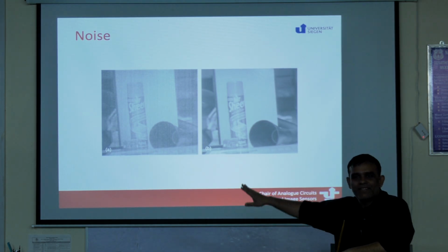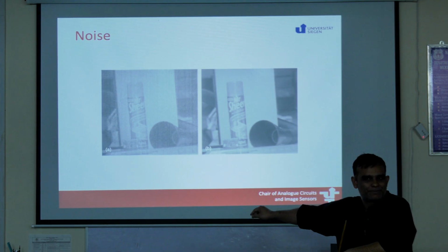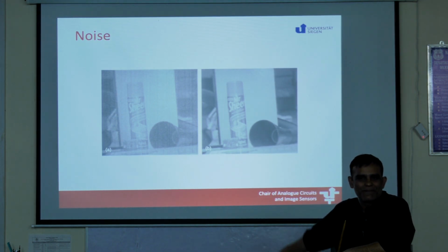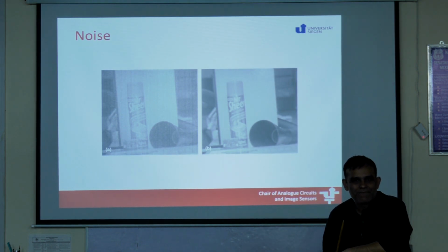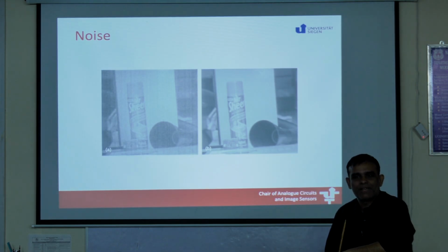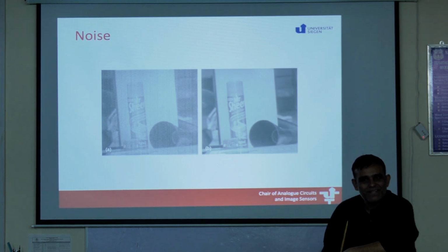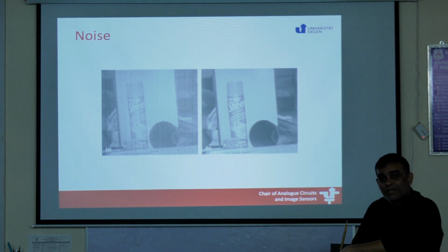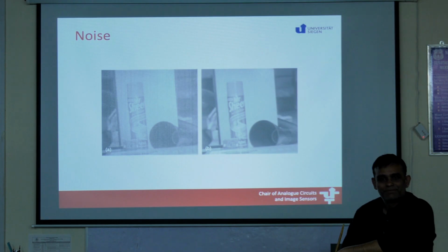So now we're dealing with non-temporal noise. But there's always going to be a temporal noise as well. Because we have charge falling on a capacitor, the current is moving, we're going to get noise. And we are worried because remember the amount of photocurrent we talked about? Femtoamperes. We have very little photocurrent and we would like to measure every small voltage difference.